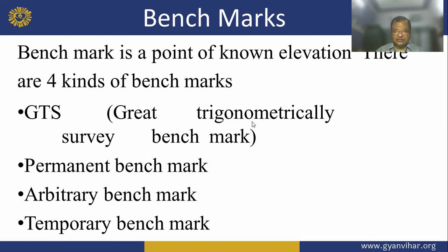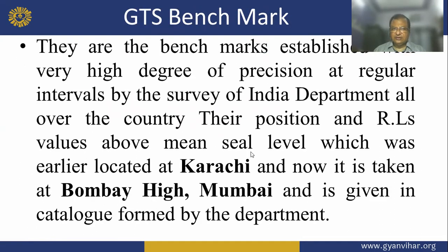Now, a benchmark is a point of known elevation. There are four kinds of benchmark. As you have read in my previous class, they are the GTS (Great Trigonometrical Survey) benchmark, permanent benchmark, arbitrary benchmark, and temporary benchmark. What is the GTS benchmark?